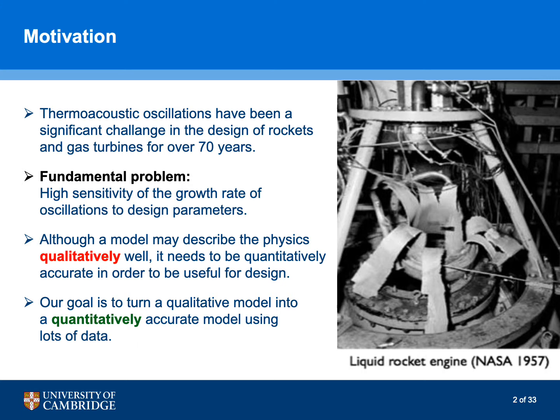Thermoacoustic oscillations arise because of the interaction between acoustic waves inside the duct or a combustion chamber and heat release rate fluctuations at the flame. The reason why they are relevant is because the noise and vibrations that appear as a consequence of this interaction can have catastrophic consequences. This has been a relevant problem in the design of jet and rocket engines for a very long time.